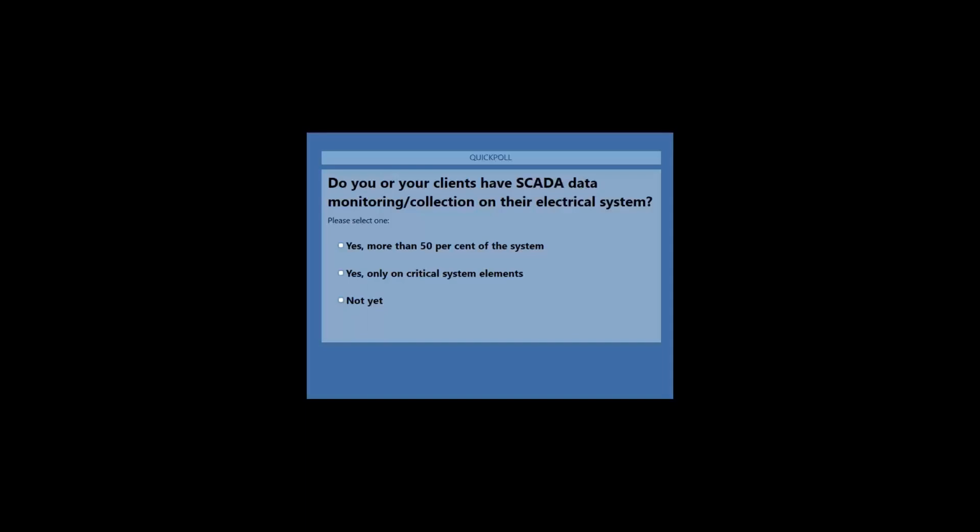And I'll amplify. So you might say, well, why would someone be doing load flow more frequently than once a week? Case in point would be if I have to do some maintenance and some large portion of my system or any portion of my system is going to be offline. What does that do to the rest of the system? Do I need to shift loads? Do I need to balance out the remaining part? And that answer comes from a load flow analysis.